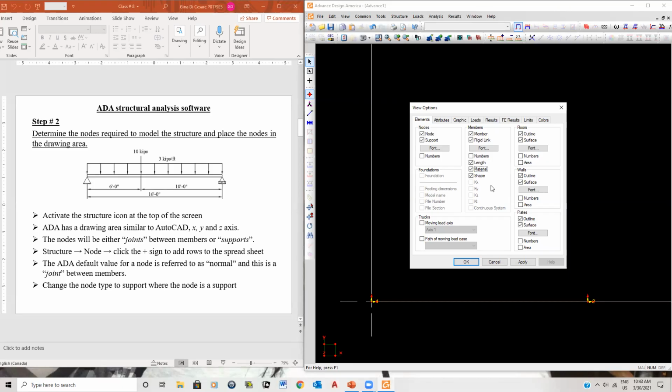So I'm assured that my nodes are rightly placed, therefore my member lengths are the same thing. The members are the right ones, because it does have a bearing, okay? It's going to have a bearing on certain results, okay? So you better make sure you have the right values. And at the same time, if you forget to assign these to the program, you will get an error message when you run the analysis.